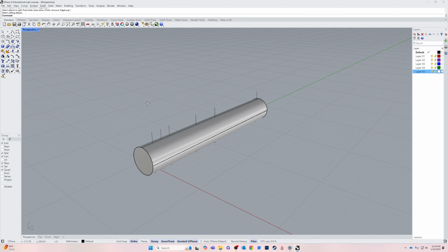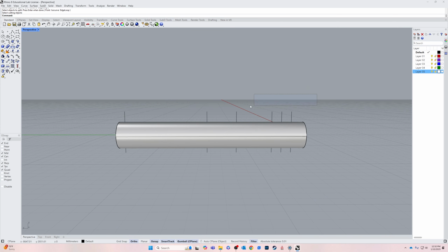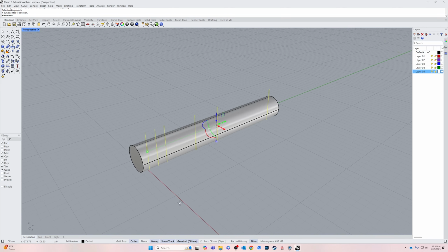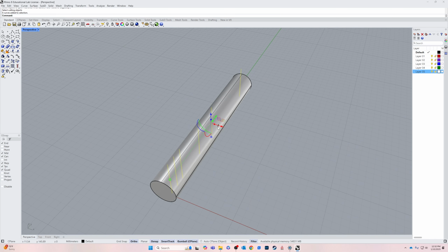I want to showcase the new tool. So our gumball now has more capabilities here. So if I select these lines here, the gumball now has this capability to split using the gumball. So this little line here is cut. And if I hold down shift, you can see I'm just hovering over it. I haven't clicked anything yet.